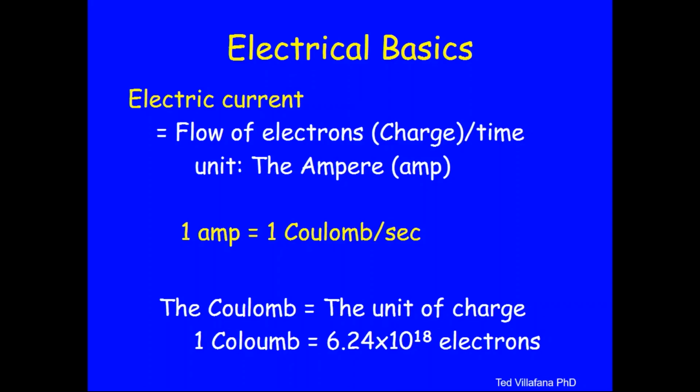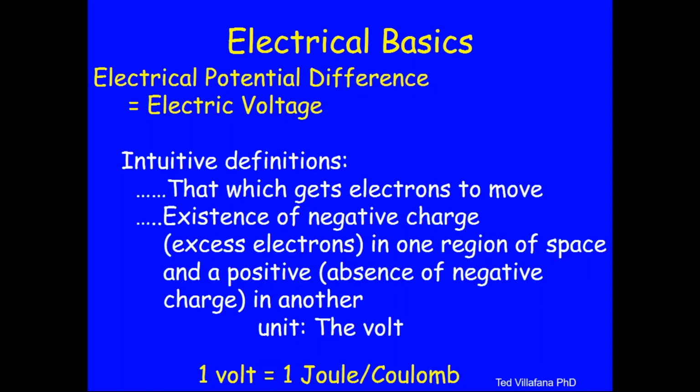The electric current concept is whenever you have electrons moving per unit time, you have electricity. The unit of electricity is the ampere. 1 amp, abbreviation of ampere, is 1 coulomb per second. A coulomb is a unit of charge. So much charge, electronic charge, moving per unit time, second. And you don't have to remember the actual value, but it's a huge number of electrons, a huge amount of charge that for 1 ampere would be moving down per unit time.